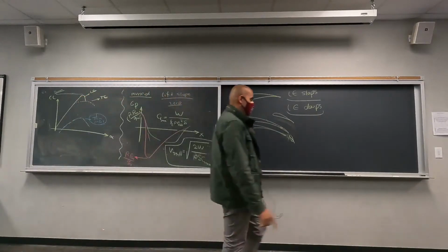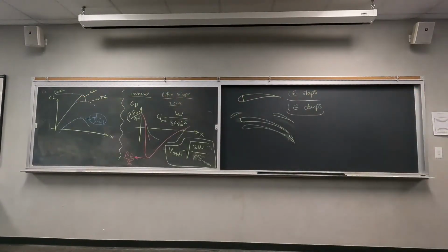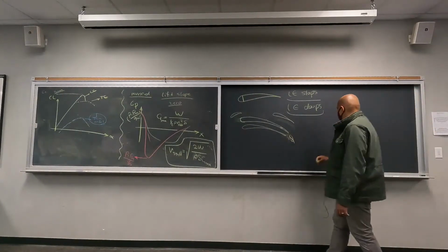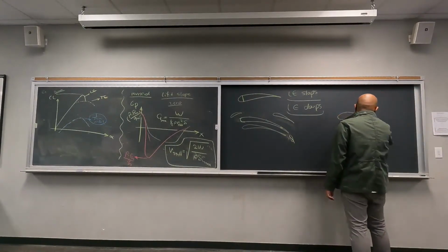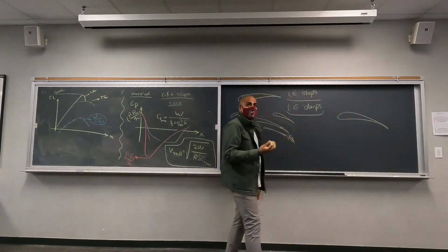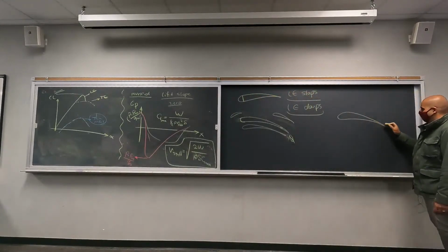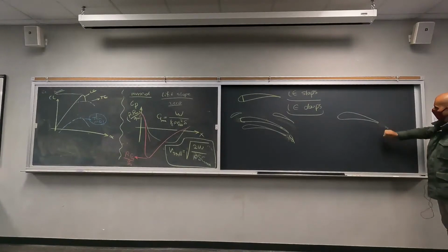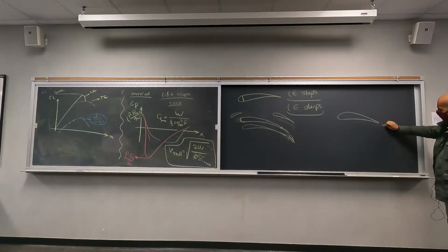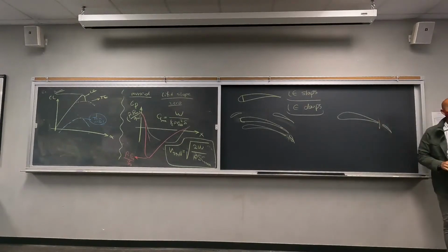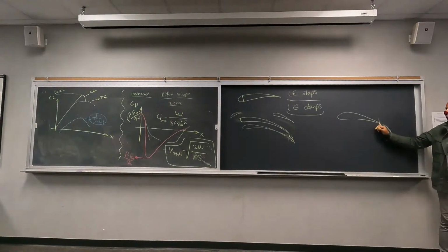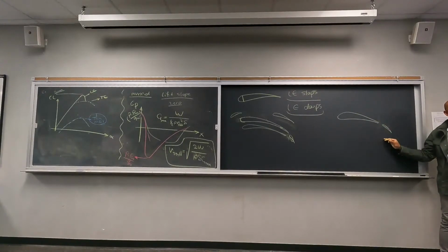That's the idea. Okay. So most of you, or some of you, talked about this mechanism. Let's say this is your wing, this is your airfoil, just to make it a little more understandable. Then you have a mechanism. It's a retractable thing, right? So at some point, this will start moving away, which means you are going to introduce a hole here, right? What will happen when you introduce a hole? It will act like a suction from the bottom, right? Because we have high pressure on the lower surface.